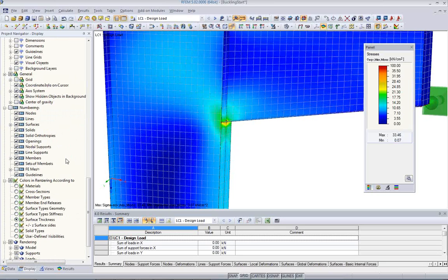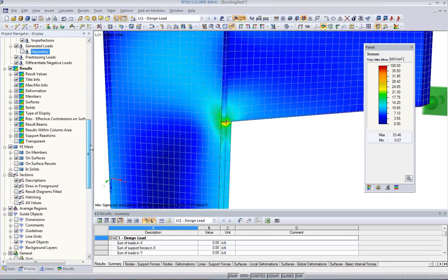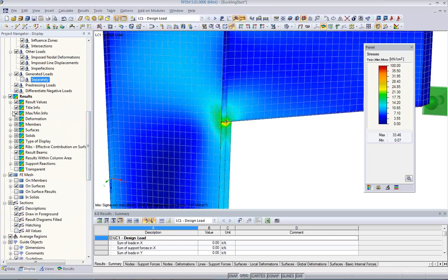But when we look at the plastic design and we change the stiffness per finite element mesh cell with one elasticity modulus, then we have a constant stiffness over the cell, and we cannot change the stiffness over the mesh at each point. So therefore, we have to look at the results constant per mesh.